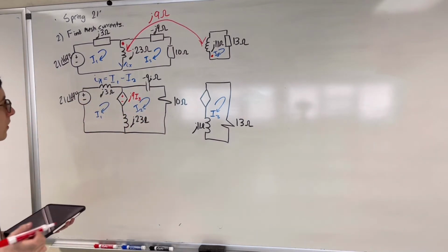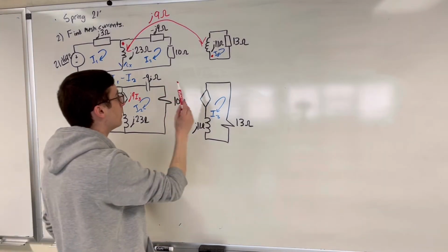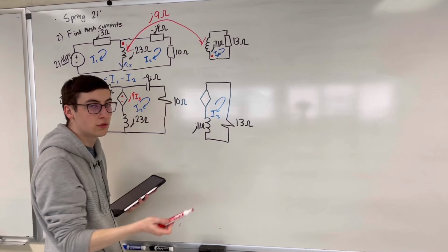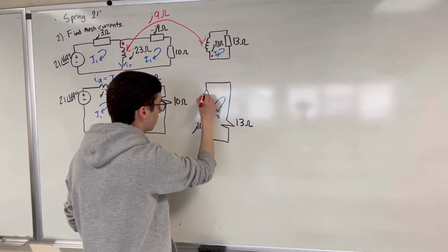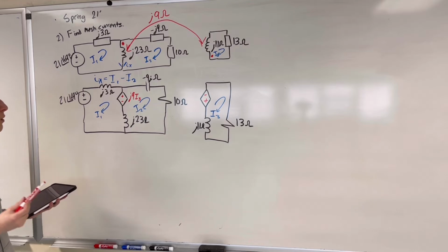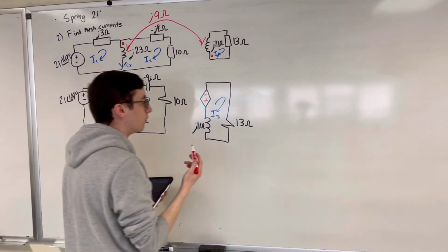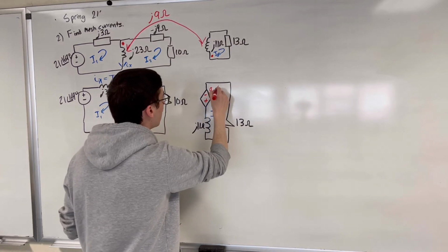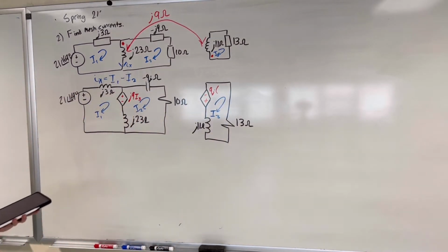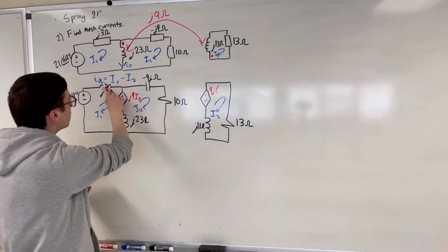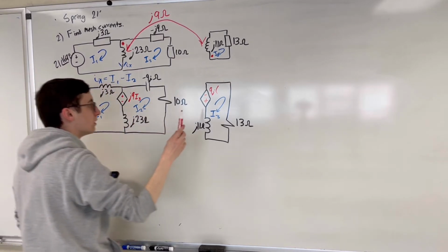All right, and now we do this dependent source, and the current is flowing up, but it's still positive dot convention, so that means we have plus minus like that. And the value of that voltage is going to be 9j multiplied by the current of the other inductor, which we defined as Ix, which is equal to I1 minus I2.